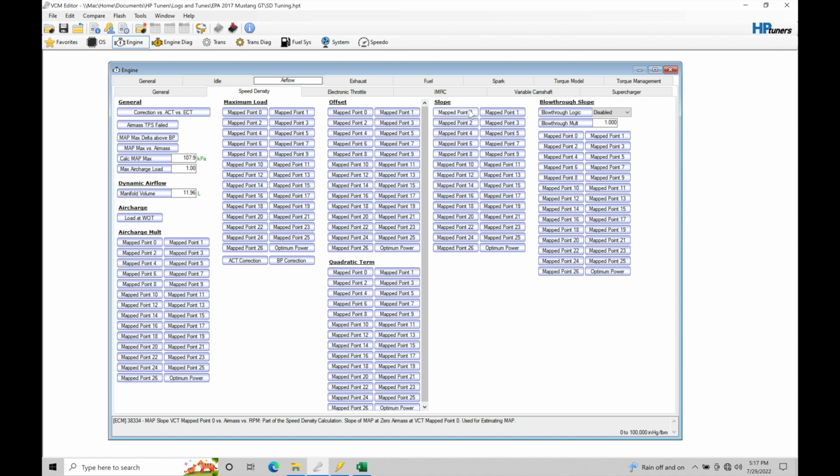Throttle mass flow is when we're able to figure out how much airflow is coming into our throttle plate. And we'll find the F-150 trucks, for example, those are going to be throttle mass flow, speed density. They go about things in a little bit different manner. Again, we're going to cover that in that tutorial. But in the Mustang applications, we can solve for a variable that we don't know for throttle mass flow. So for example, in the Mustang application, we have airflow coming into our throttle plate, measured from the air mass.